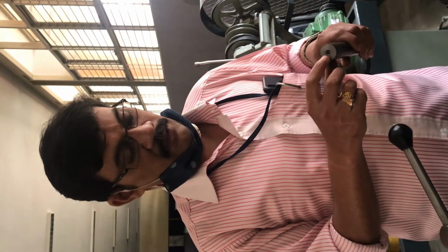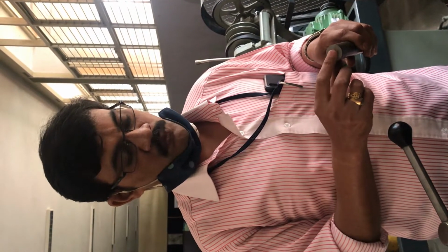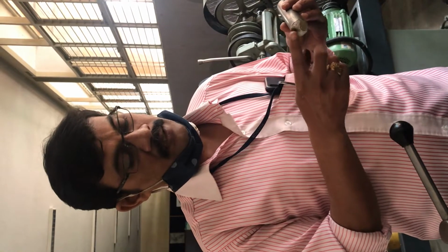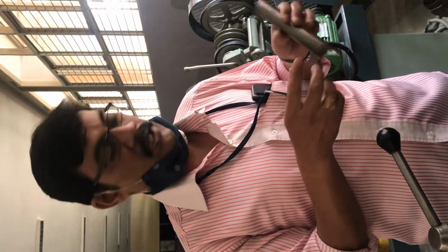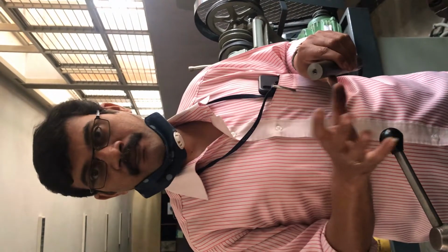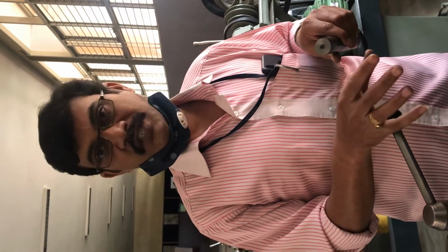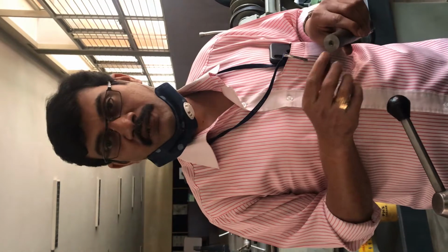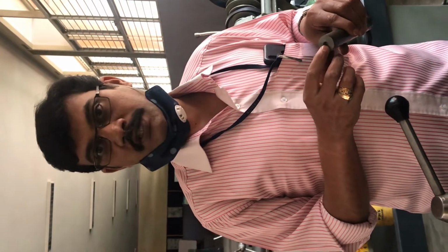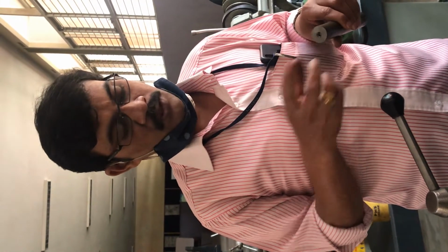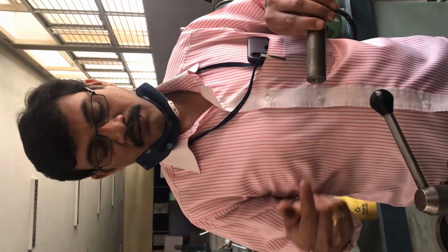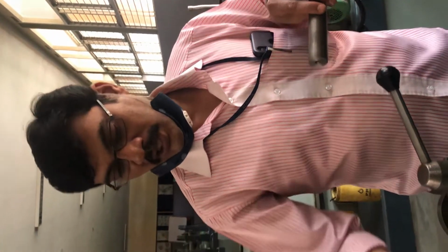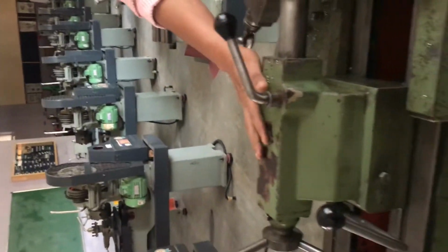And this is called centering. Already we have done centering and facing operation on one end; the other end will be blank. I will show you these two operations, because these two operations are basic. If you want to do any lathe operations, these two operations you have to do first. Centering we use for holding purposes. One end will be held by the chuck, and the other end we have to support with the tailstock along with the dead center.